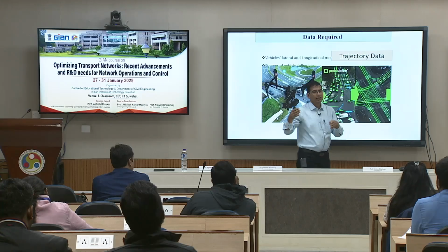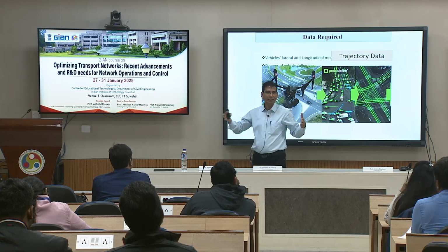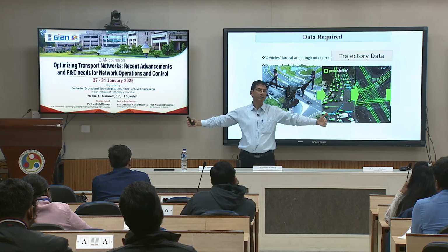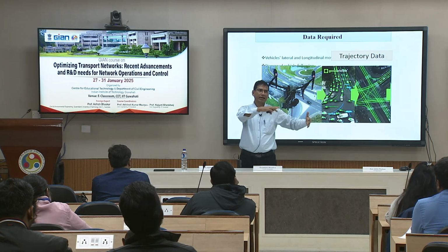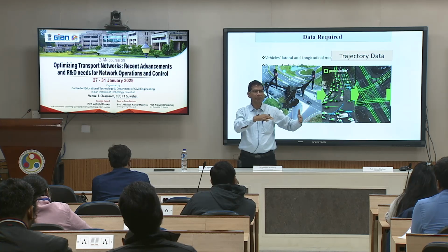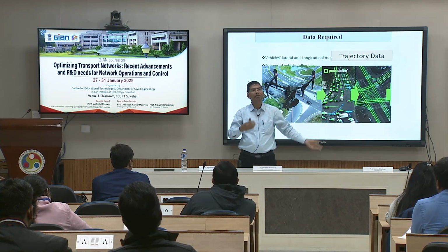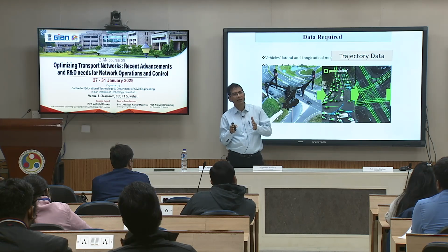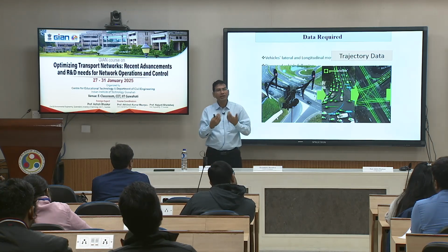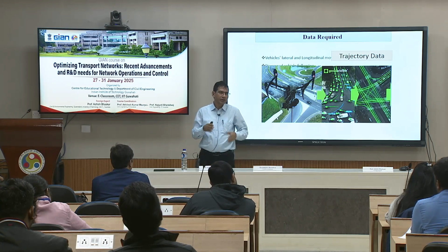There are two things, we will talk in detail. The minute count is not important; here duration is also important, and stretch is also important. If you want to study car following or overtaking, you need a certain stretch of information, otherwise the overtaking will not be completed. If you have just 100 meters, you will not be able to study most of the car following behavior. So you need a longer stretch, plus duration obviously is required.